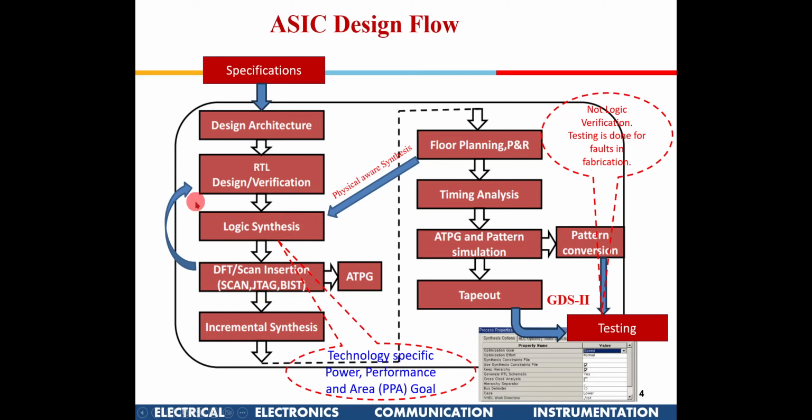So once you do that, you finish off this particular loop where you have inserted your extra modules which will enable testing. Then there would be an incremental synthesis. That means, since you are in the synthesis, some extra gates will be required to be synthesized because of this.